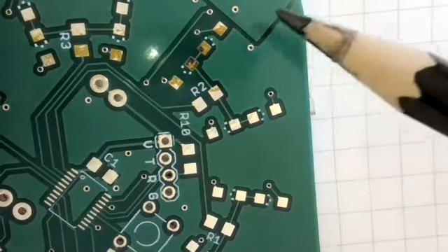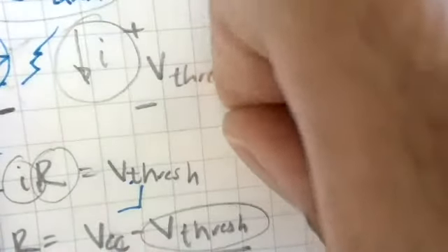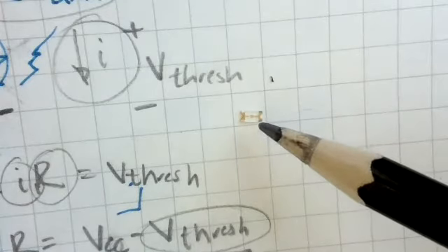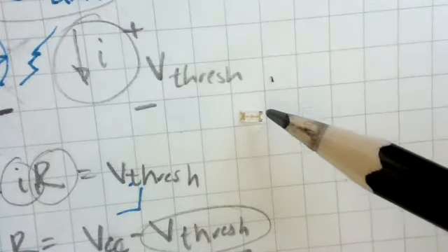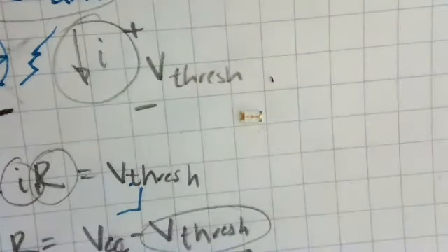All right, so how do you know when you look at a diode like this which direction the current is supposed to be pointing? Well, on the back of it, you can see there's a little arrow that's drawn. That's helpful, but it's not that helpful because when you're soldering it, you've got to put it down this way, right? So let me flip it over again. And what we see is that there is an arrow going in that direction. And now to very carefully flip it over, use tweezers if you're going to do this. Don't use your fingers. You can see that there's a little bit of green on this side. So that tells you that that side is the cathode, the ground side, the negative side. But don't do it that way. That's not the right way to do it.